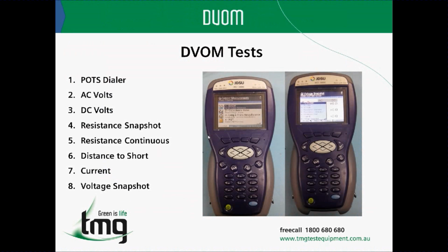Our main priority prior to employing a service on a new and/or existing line is to ensure that the line meets the basic specification criteria in regards to voltage, resistance, capacitance and current measurements. That takes us to the first most important menu of functionality within the HST3000,